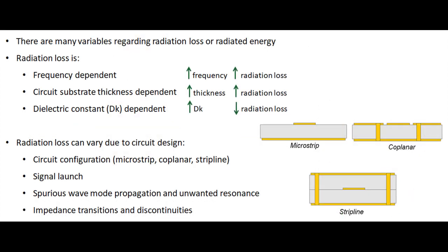Shown here is more information about radiation, and this is really important to understand for antennas. Again, we're really thinking more in the transmit mode where you're wanting to radiate energy. Now, insertion loss is made up of 4 different components, and they are all summed together. What we have for insertion loss is dielectric loss, conductor loss, radiation loss, and leakage loss. And typically, you do not want radiation loss unless you're wanting to transmit and radiate energy. Then you do want radiation loss, but only at the patch. So the feed line that's bringing energy into the antenna structure should not radiate, and if it does, you lose some energy that way. You really want the feed line to have no radiation loss and the patch to have maximum radiation.